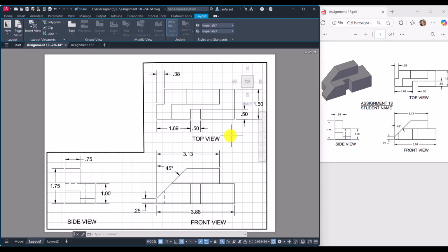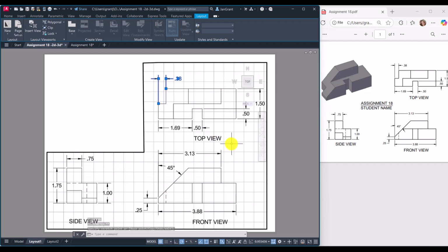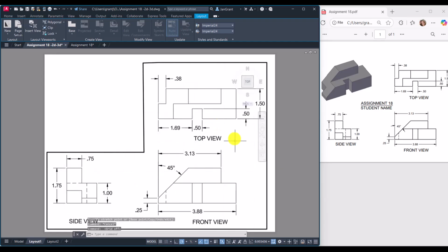And, since you're here, if you needed to pull something down, you're inside the viewport. If I needed to pull this down, I could click on it, click inside the script and pull it down a little bit more, which I don't really need to. So this is where you're going to make a few changes to make it fit in here. And then you can come down here and turn the grid off if you want, right there at the bottom. Makes it look a little bit better.